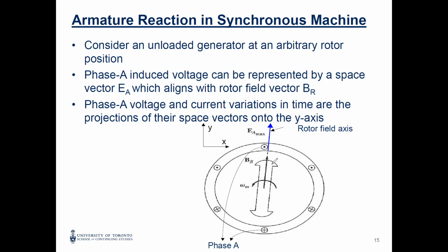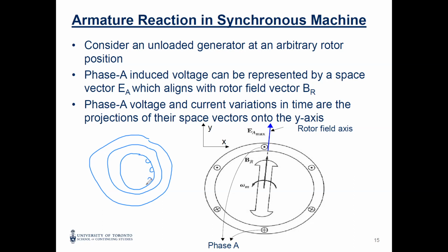One thing that I can add here, can you see this one? We call it a salient machine, salient because you can see the poles. Sometimes, and in reality too, you can find that the rotor is a circle, and we include the field winding in slots, similar to what we do for the stator. This one we call non-salient, or sometimes cylindrical.